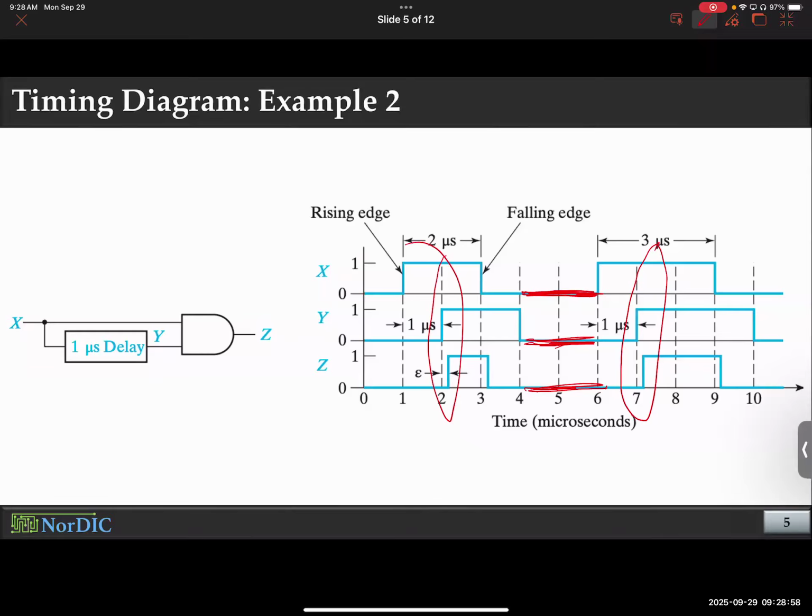During transition, it takes some time to charge up the capacitance. Do you guys remember the current flowing through a capacitor? C dV/dt. Okay, when the voltage stays constant, what is dV/dt? Rate of change of voltage. What is that? 0. So no current through the capacitor, no charging or discharging. So there is no delay. That's why in DC mode, when nothing is changing, you are all good.